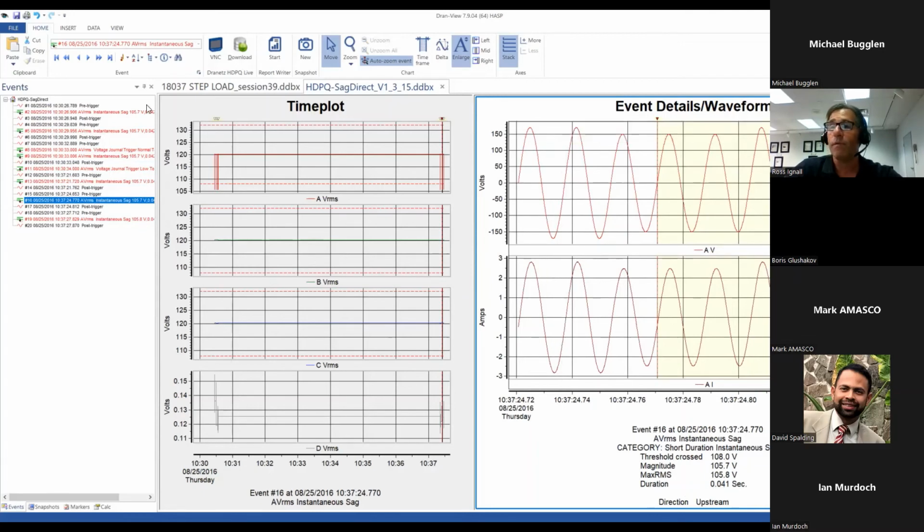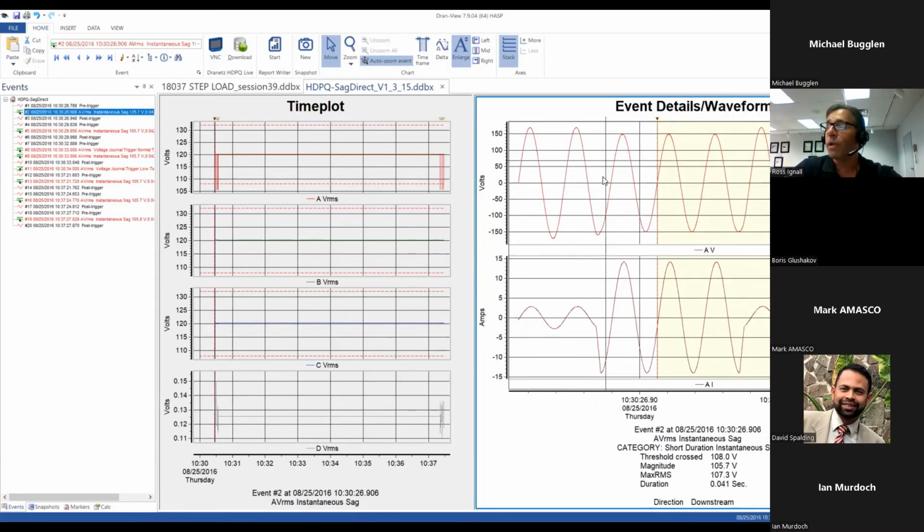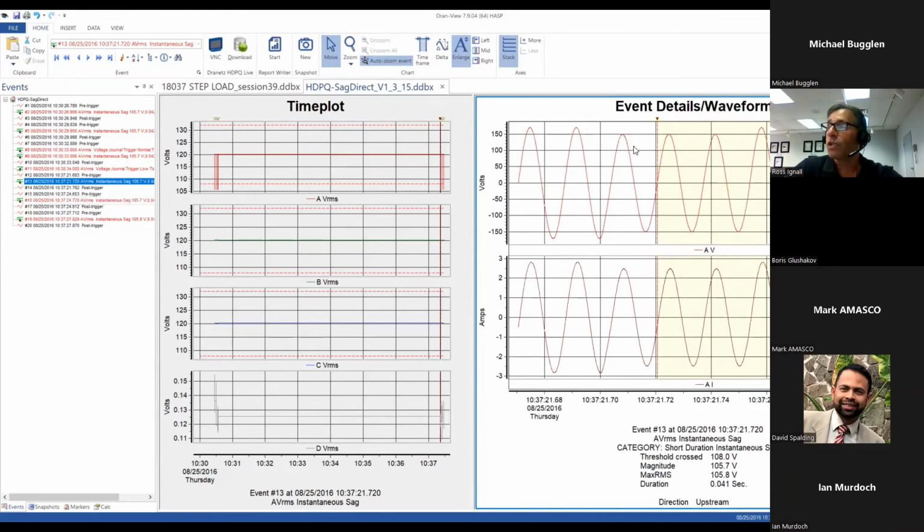So again, as a review, the voltage and current go in opposite directions, specifically for a load-based something turning on, the voltage goes down, the current goes up. That's a downstream directivity for that event. If the voltage and current go down at the same time, it's an upstream. Consider no voltage, no current, right? You can't draw current on a supply that's being temporarily disconnected or has an issue. Okay, so that's the difference in directivity and an upstream and a downstream event.